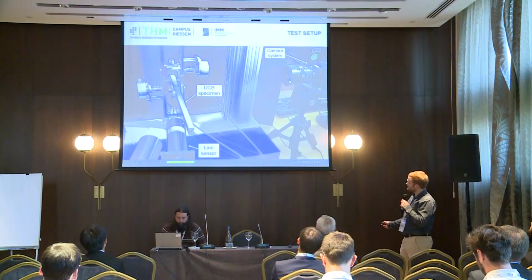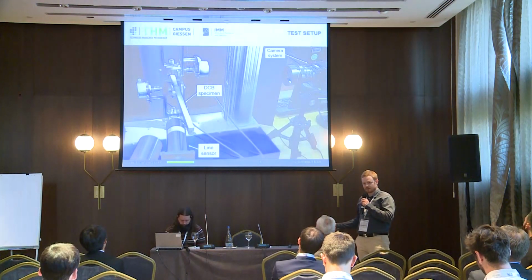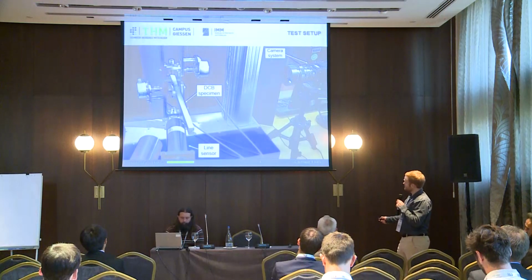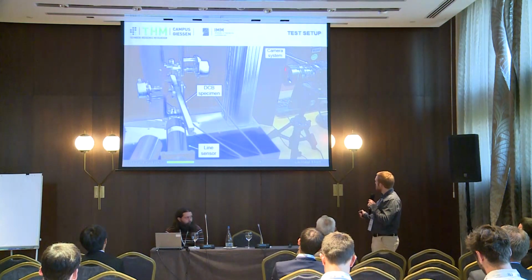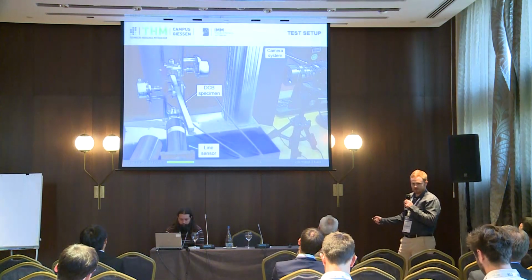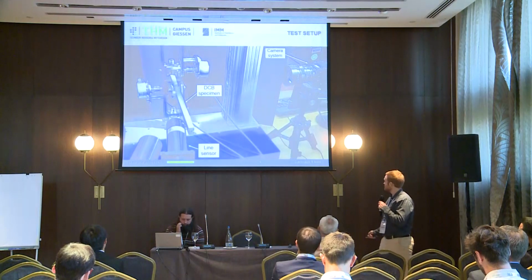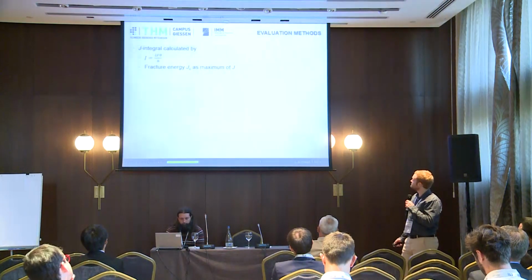This line sensor detects variations in contrast between the white measuring flags and the black background, and this is where you get the crack opening displacement from. We used another camera system on the right side, which is focused on the edge of the specimen, to get pictures from the side to observe fracture behavior.